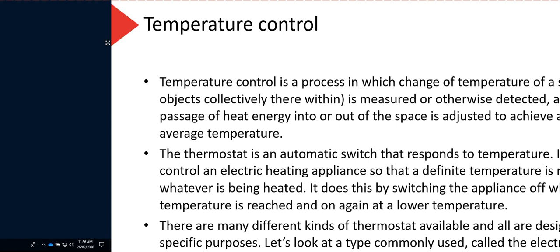The thermostat is set up to measure the temperature of whatever it is that's being heated. If it's a hot water cylinder, then we have to have our thermostat stuck next to, on top of the hot water cylinder. If it was a heater, it's inside the heater. If it was an air conditioning unit or heat pump, then it's inside the heat pump. It's a fairly coarse measure of temperature control, because obviously it is going to just go full bore while it's on, and then nothing while it's off. Although there are some exceptions to that, which I'll talk about shortly as we go through these slides.